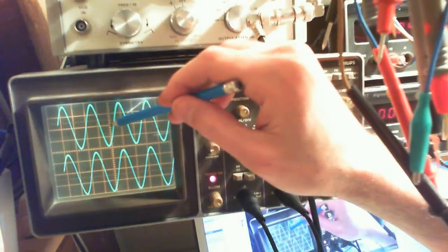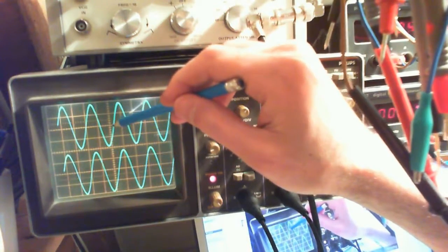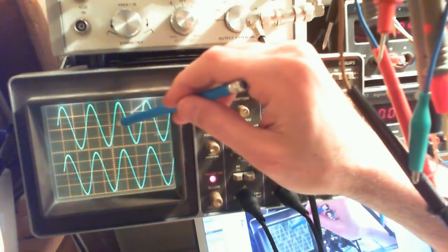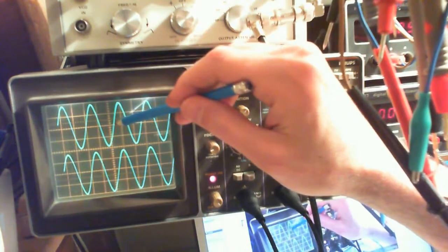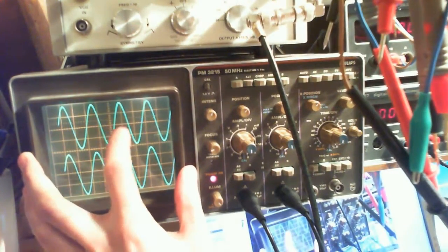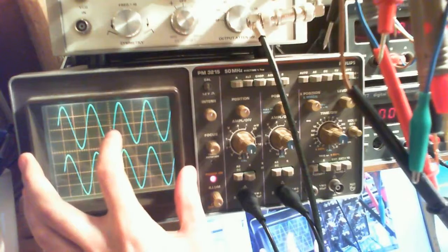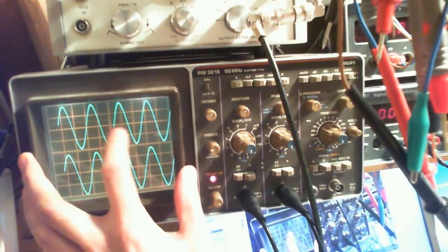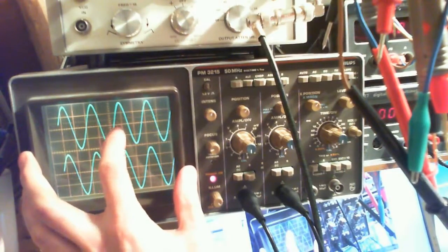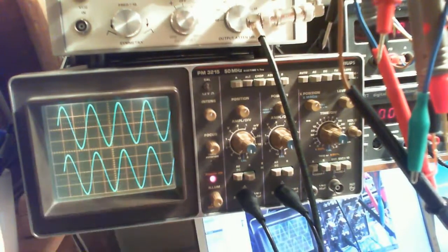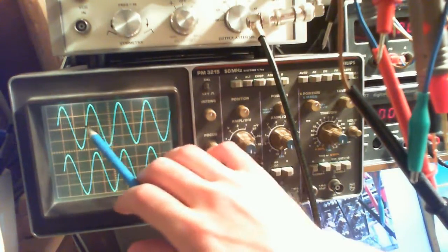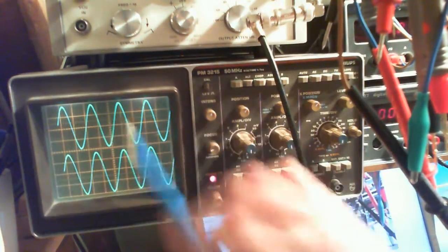So you see that over here, 1, 2, point 2.2, basically that's 2.4. We're very close to 2.4, so I take it as 2.38, for example. That 2.38 horizontal units is the period of your input signal.